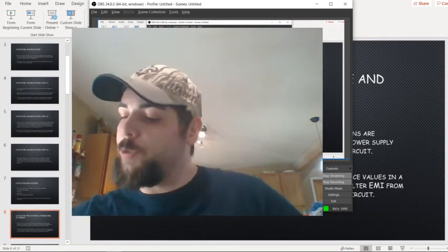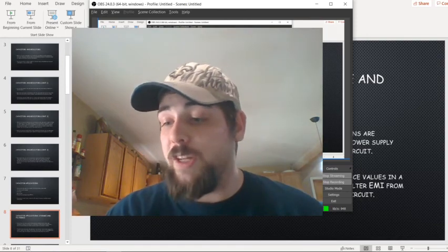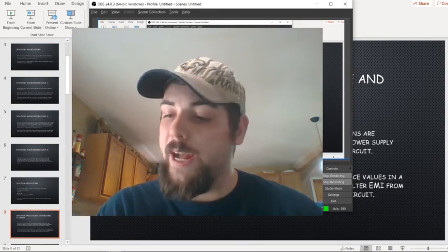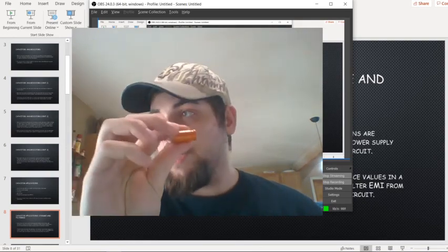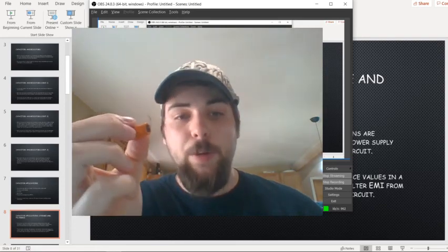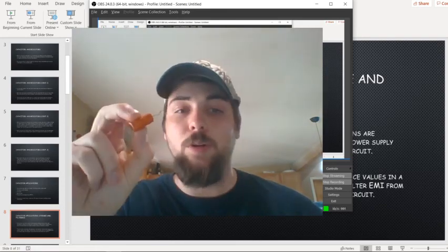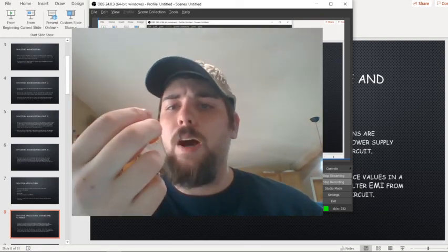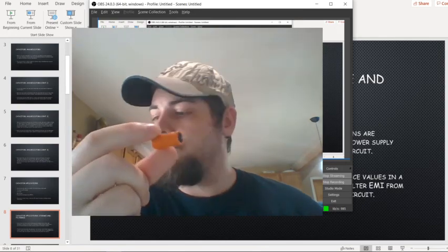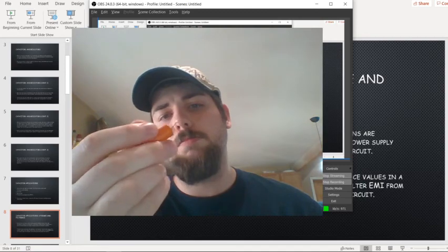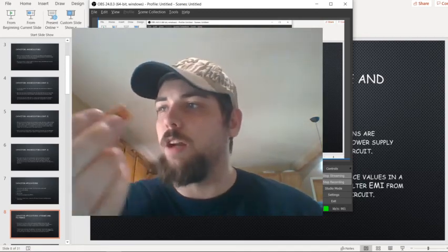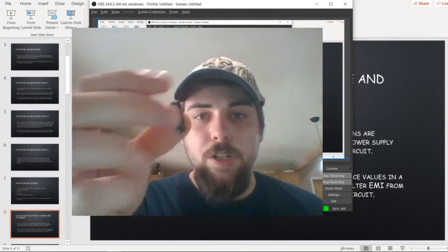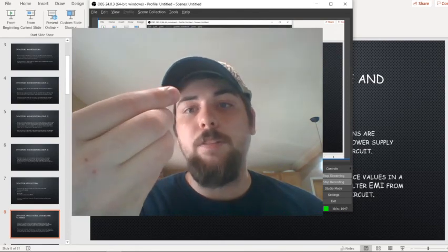And those are generally used because they have a large capacitance value, and in this case, it's 1,000 microfarad or 1 millifarad, but it's 16 volts. So you're able to get a lot of capacitance value out of these. And in certain cases, this one came out of an old radio, like a Ford car radio that I took apart. And this one is interesting to me because it's orange. You don't really see that color very often. But generally speaking, you'll see more electrolytic capacitors in this fashion, which is 180 microfarad at 50 volts.